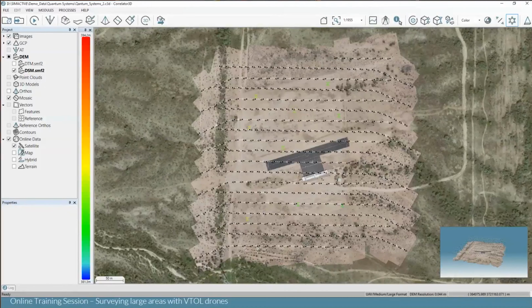First, you will have to take a look at your quality reports, because it will have a great impact on the ortho rectification, but also on the DTM generation. I will show you the quality report in a few minutes. You will also probably want to edit your DTM or take a look at the surface elevations, because it will also have an impact on the ortho rectification, so this is something you really want to check if you have any residual errors on the altimetric values.